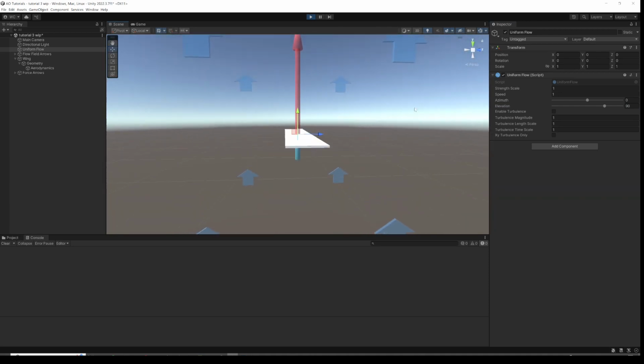It's just getting drag, no lift, but as I carry on going, the wing is now effectively flying backwards, so the wind's coming from towards the trailing edge, but it's at a positive angle of attack on the trailing edge, and we're generating lift that way. So wings do work backwards. They're not quite as good as when they're working forwards, but they will produce some lift. Great, so let's set this to say 20 degrees angle of attack.